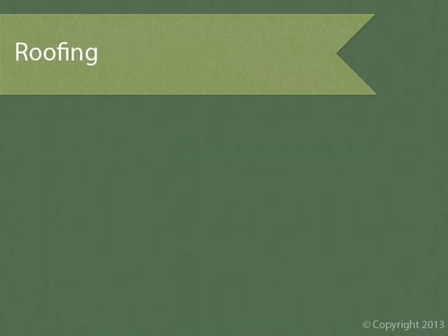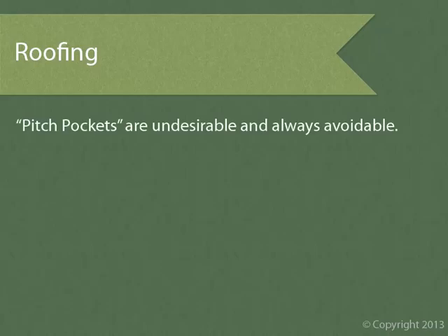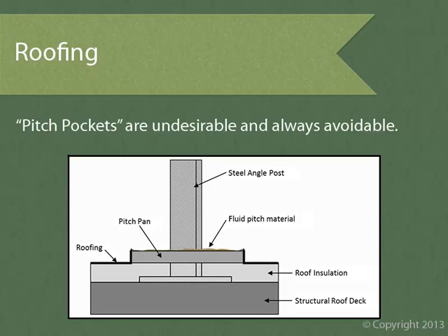Okay, next on the list is a roofing example. Avoiding pitch pockets whenever possible is an excellent construction practice. These things are a pet peeve of many contractors, owners, architects, and especially building maintenance supervisors, and I discourage their use on each and every project that I'm involved with. Roof jacks are designed to wrap round or nearly round objects. About the furthest you can stray from round and still use a roof jack is typically tube steel.